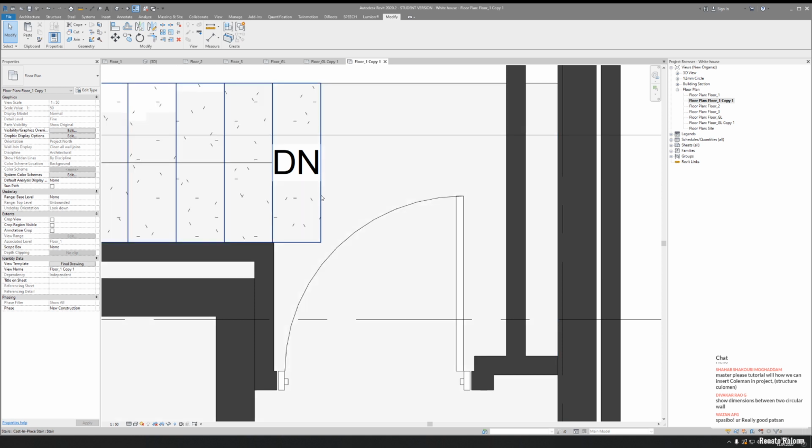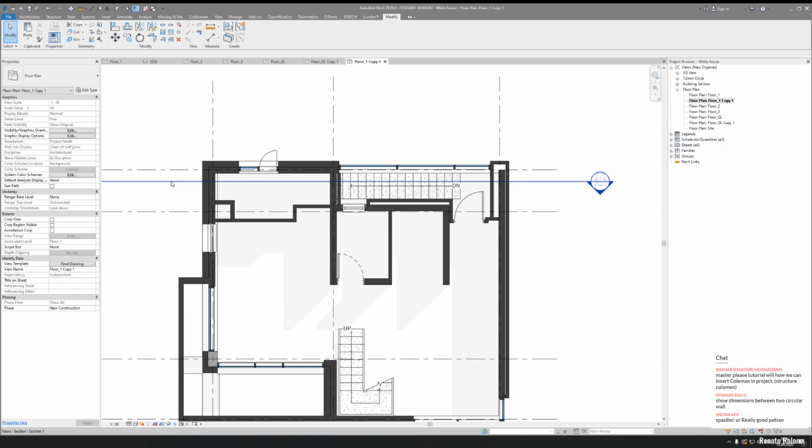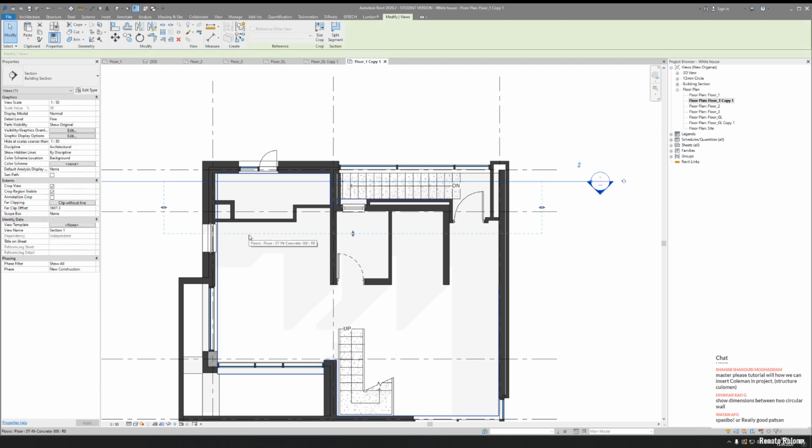For example, we have a situation here, right? You can do the same thing here if you want. So do it whenever you want, but be careful with all these dash lines, okay? Because sometimes people don't like it. For example, another problem: you have the section here. By some standards, like for example UK standards, the Russian standards, and I think the Singaporean standards, your line shouldn't go inside your drawing.